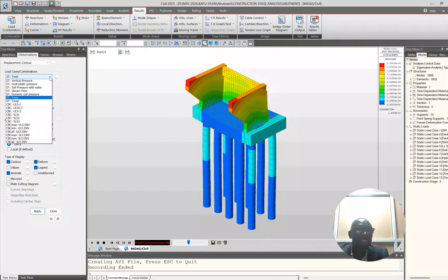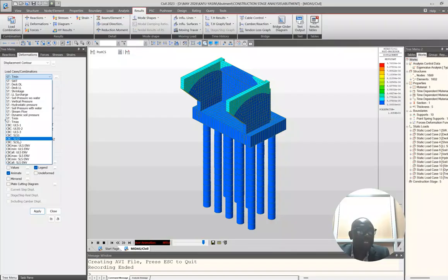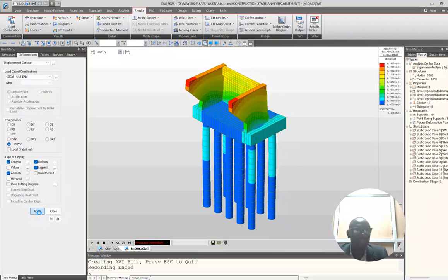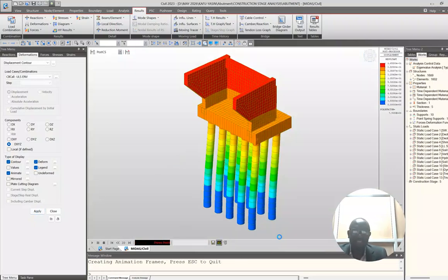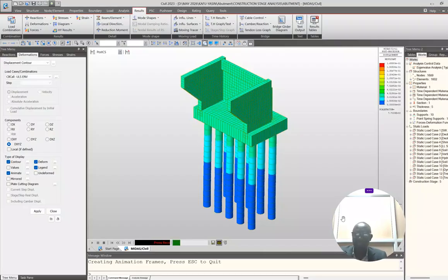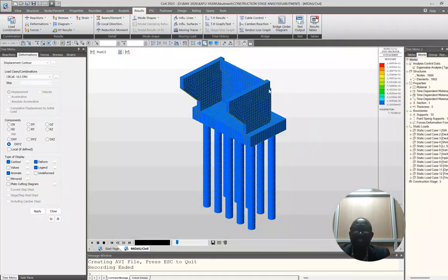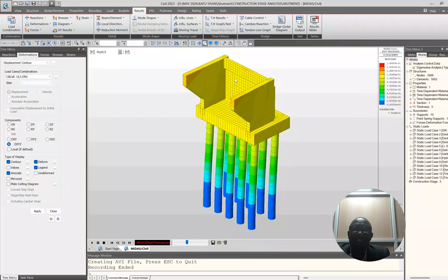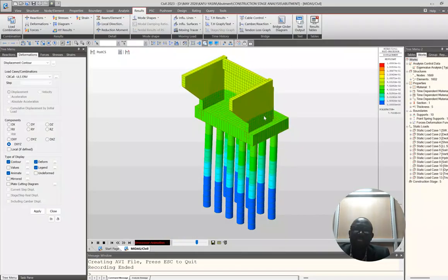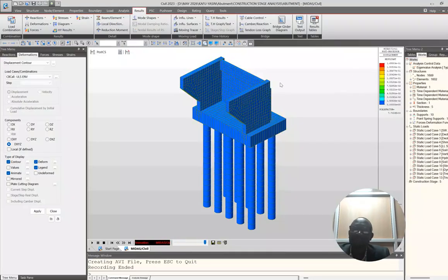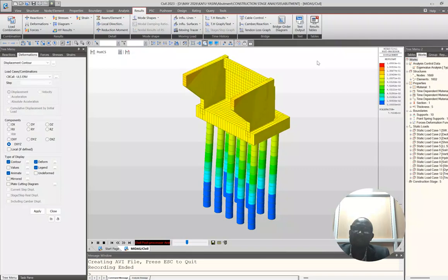So if you now look at the global case where you have applied all these loads, with temperature and the rest, it behaves by looking at the effective, resultant load. If you look at this, we have the braking force here from the deck dead load, and the deck live load also has an element of braking. So in a way, an effective behavior. This will generate some movement that needs to be taken care of, whereby your expansion joint and other support systems also will be taken care of.